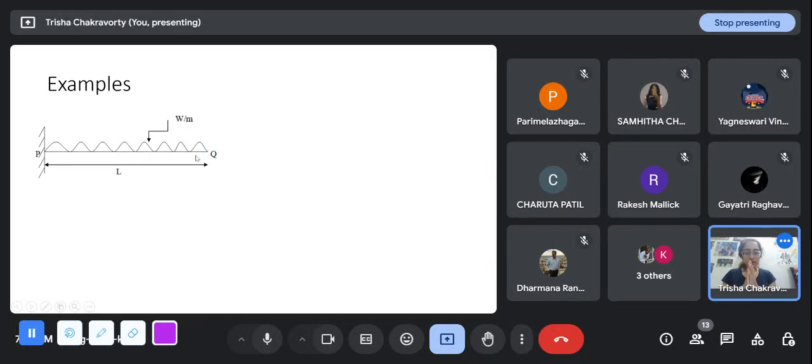So if we are told that this is a beam element, then that mode is completely eliminated, we are not going to consider that. Then we will have two equilibrium equations: summation of Fy will be 0 and summation of moment about the z direction will be 0. And we have two support reactions, one in the y direction and one a moment along the z axis. So anyway, the result is that it is still an indeterminate system. But if it is given as a beam element, do not consider the displacement along the x axis.